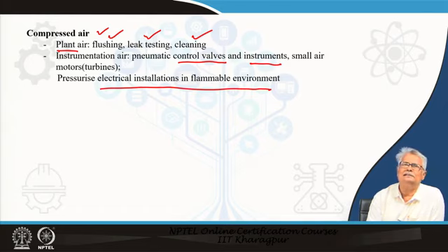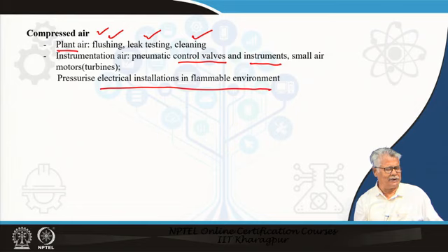Through all the leakages present, it leaks out, but the inside pressure naturally is more than the ambient, and the ambient inflammable environment cannot intrude inside. So, that makes such enclosures safer against any electrical spark and its contact and generating disastrous situations in a flammable environment.